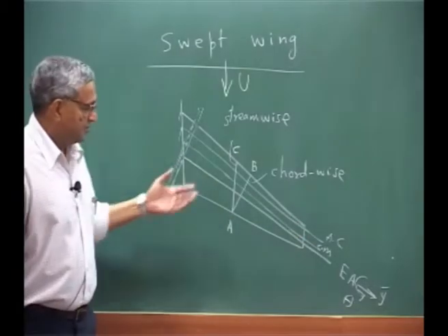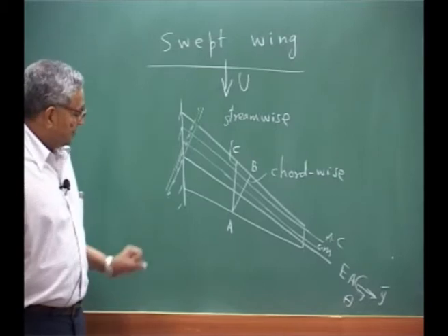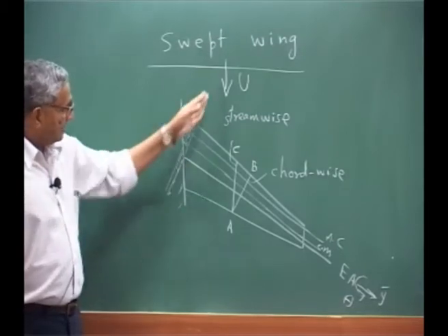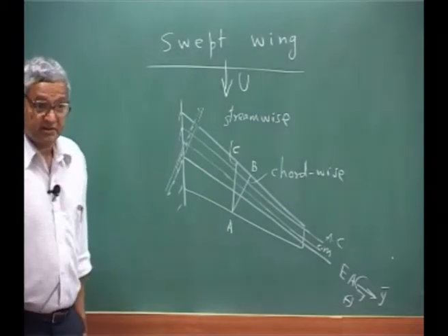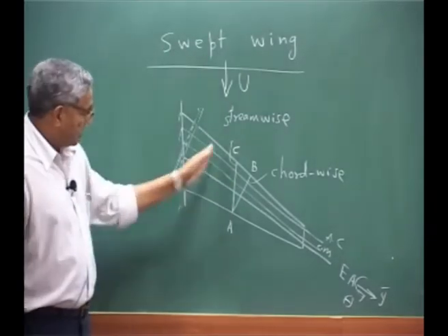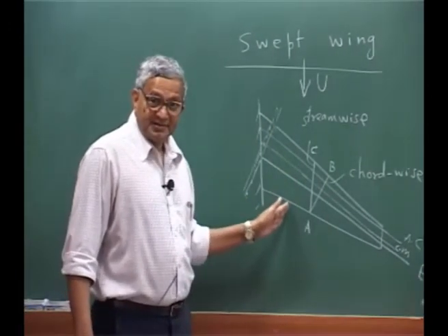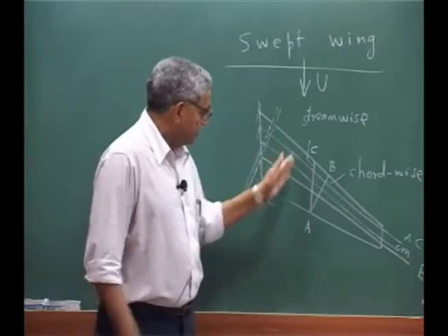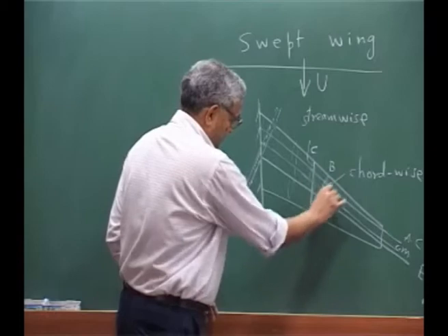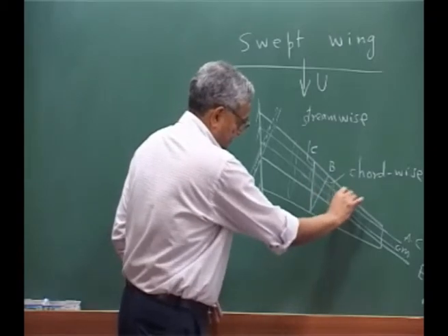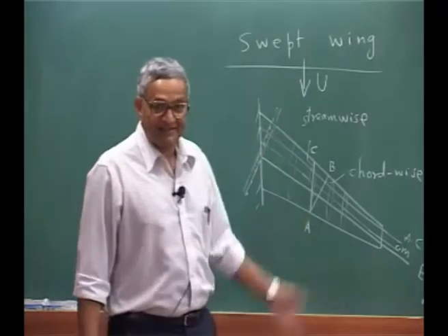a beam. Now if you look at this, I have one is streamwise if I stiffen my structure. That means all the ribs in the structure I place like this. Okay? That means I have stiffened my structure in the streamwise direction.